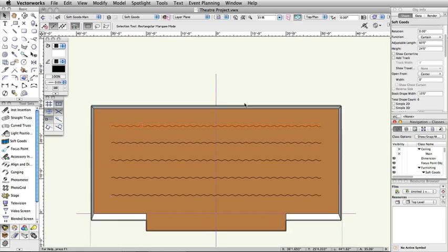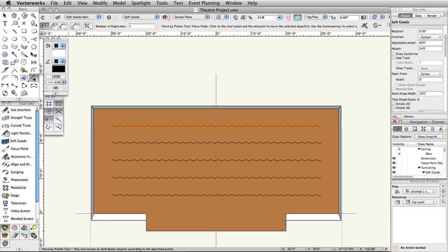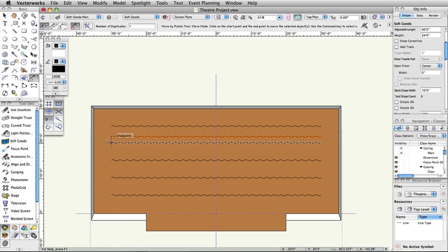With the Downstage curtain still selected, activate the Move by Points tool from the basic palette. In the toolbar, activate the Move mode, the Object Retention mode, and set the number of duplicates to 1. Move your cursor to the stage right end of the Downstage curtain object. When the Smart Cursor cue insertion point appears, click once and move the cursor upstage. Press the Tab key to enter the floating data bar. Set the length to 3 feet. Press Tab. Set the angle to -90 degrees. And press Enter or Return twice.